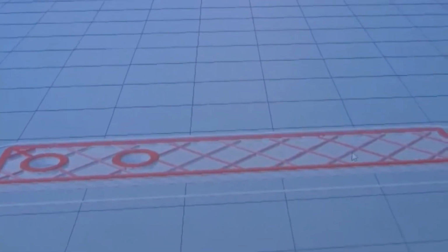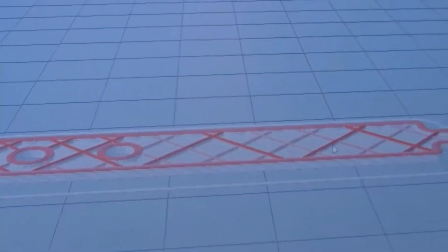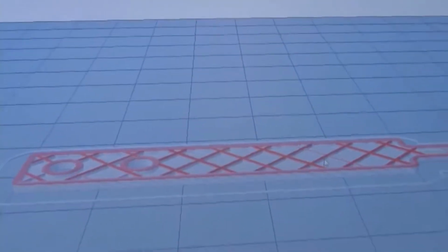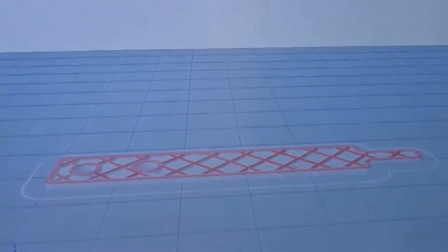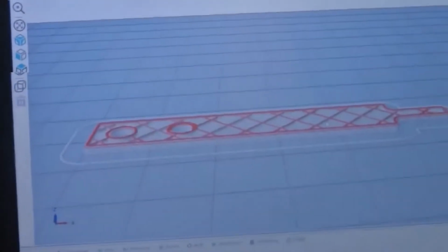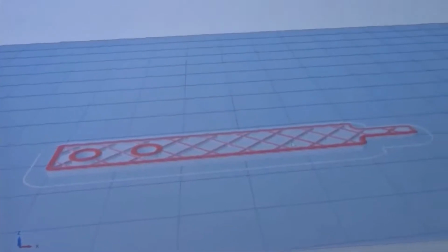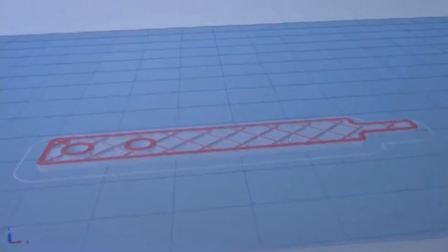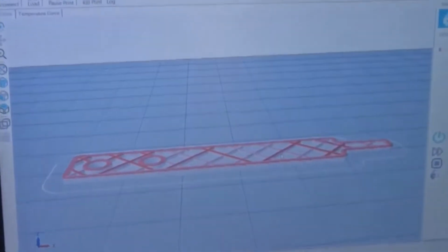This is the software with which you have to control the printing. This is not the software in which you make the design. You make the design using conventional CAD software like SolidWorks, ProE, etc. And then you have to convert it, as I have mentioned, to STL files. Then the STL files have to be again converted to something that this machine can understand, which is machine code. It is the same as what you do in assembly programming in microprocessors. But here the machine is different, so the code will also be different.